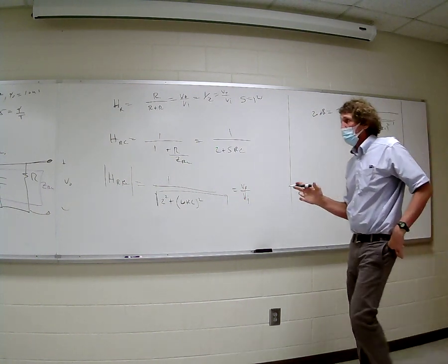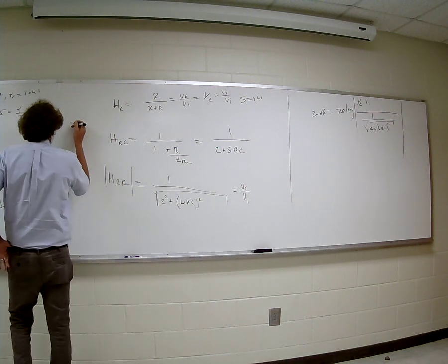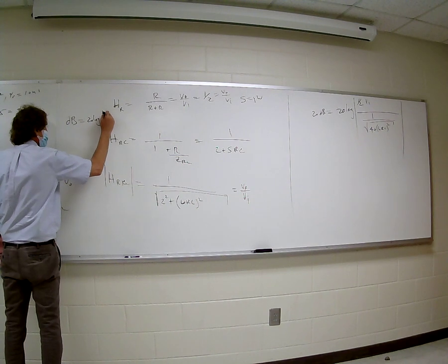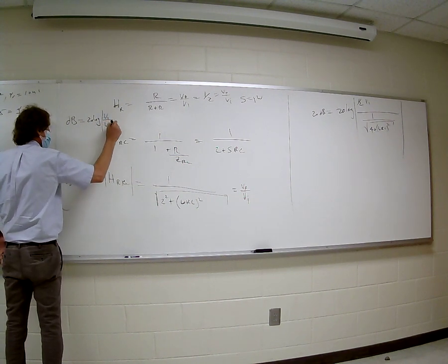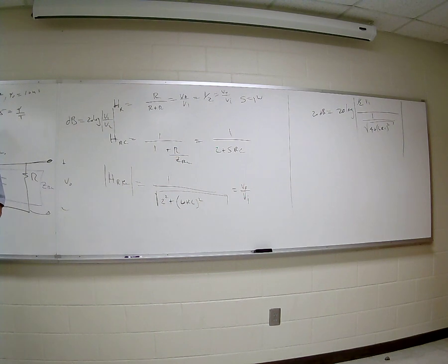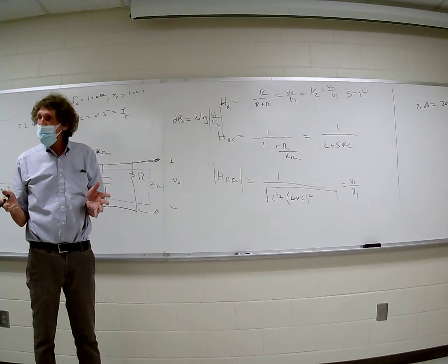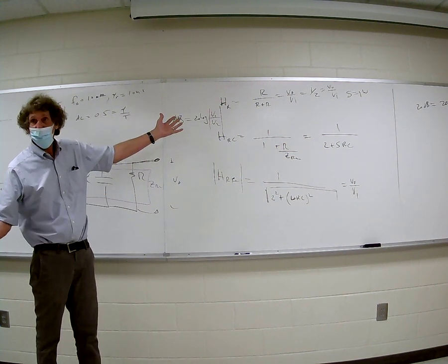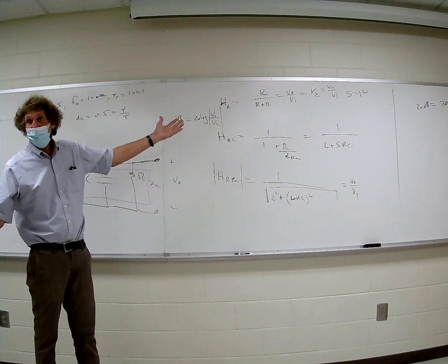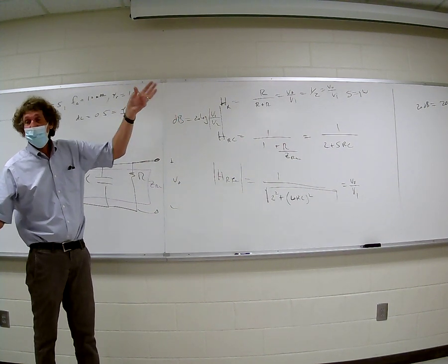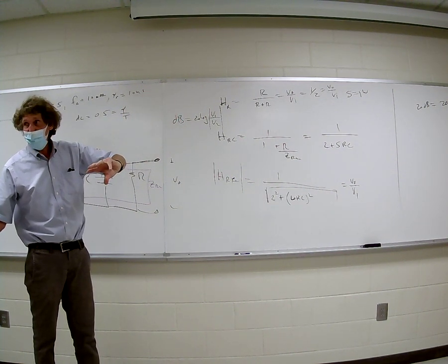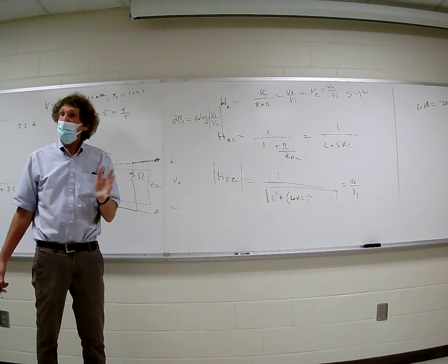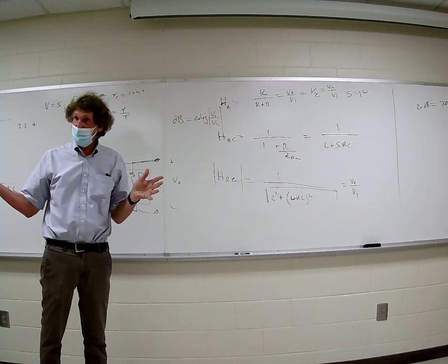Because remember with dB, if we're talking about voltage, when we talk about dB of anything, that's 20 times the log of the ratio of voltages, V1, V2. In our case, V2 is with the filter, V1 is without. And remember, this filter is going to reduce, so in order to get a positive value for dB, because they said positive 20 dB, it's always that way. You've got to put the filtering voltage below there because it's going to be less, right? So if you have the ratio of something divided by something less than it, it would be greater than 1, and therefore the log would be positive. Do you follow me on this, class?